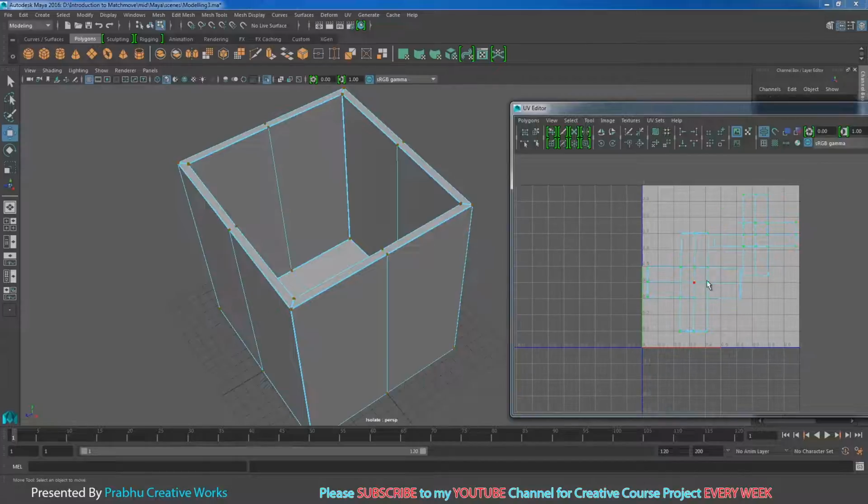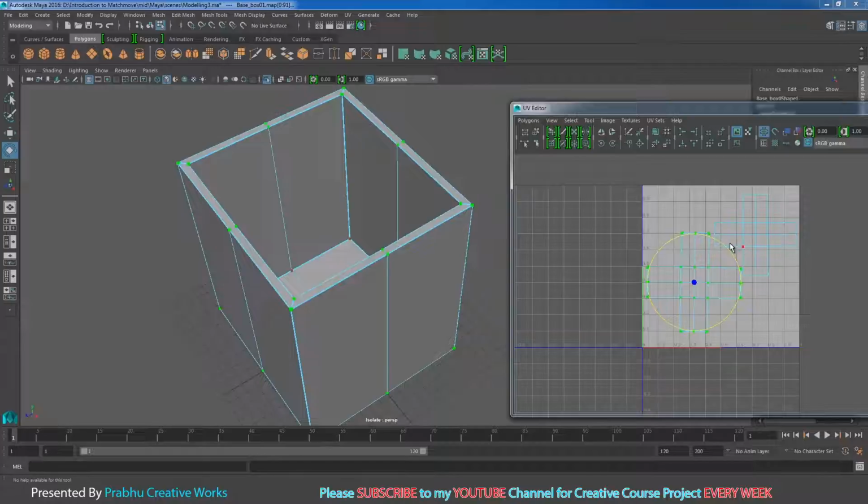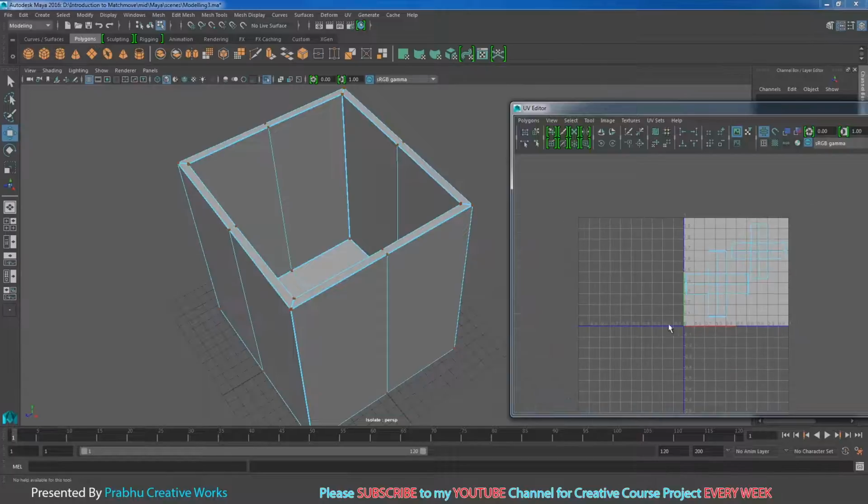So I will select this UV shell and press E and rotate like this, and press W and move this one a little bit. So now our box UV is perfectly separated.